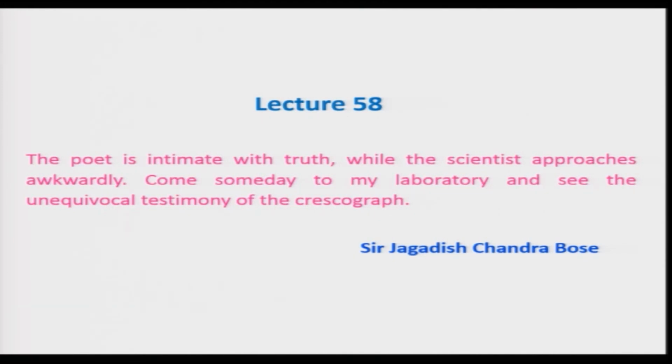Let us recall what we learned in the last lecture. We initiated discussion on the hybrid propellant rocket engine and looked at its historical evolution. Then we moved into the various components of the hybrid propellant rocket engine and the fuel grain configurations, and we looked very briefly at the complex processes involved during hybrid propellant combustion. In the process we derived a semi-empirical relationship for regression rate, and we will be discussing that a little more.